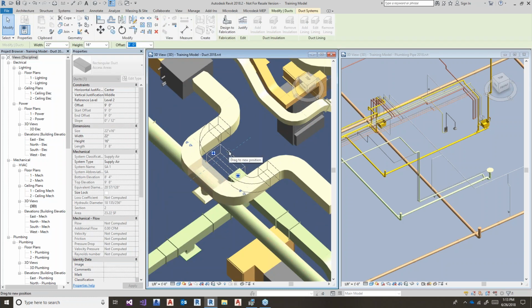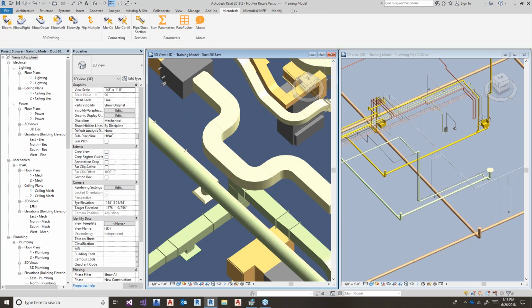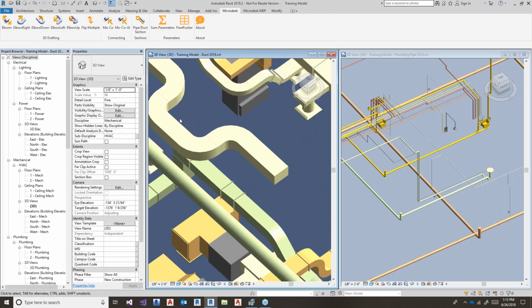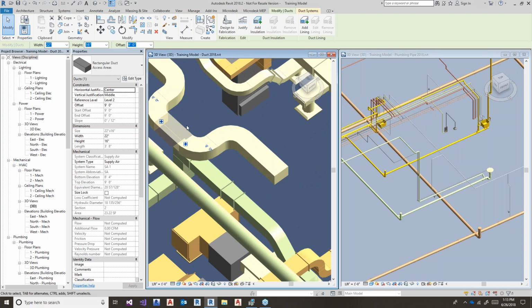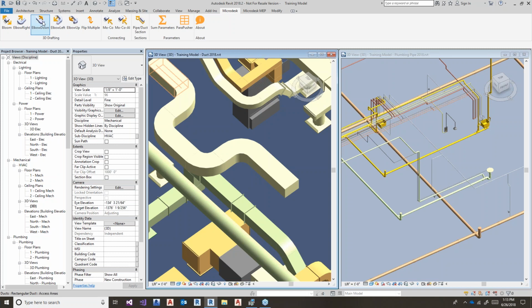And then at that point, maybe I'm a designer, so I'm not too concerned about the precise distance. I just need to get in the ballpark of 3 to 4 inches away from structural steel. And if I crush the insulation a little bit, it's not that big of a deal. But this at least gives me something to bite onto, and then I can use drag and drop, or I could use the arrow keys on the keyboard to nudge things, and that gets me approximately where I need to be.